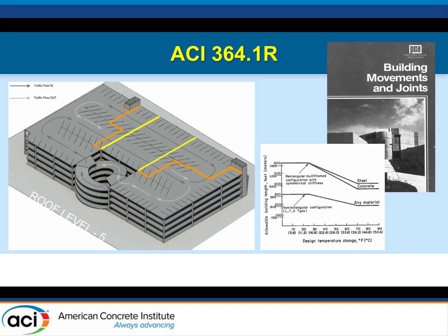But these are sort of empirical guidelines. And I found over the years that you stretch the limits or people interpret these things differently. So there's a chart in there that, for different types of building structures, says this is where you should have expansion joints, and maybe this is what the size of the expansion joints ought to be. So I found the guide good from a design standpoint, but when we look at structures, it's not uncommon that we find they either should have expansion joints and they were never put in, which is the case on the left-hand side.